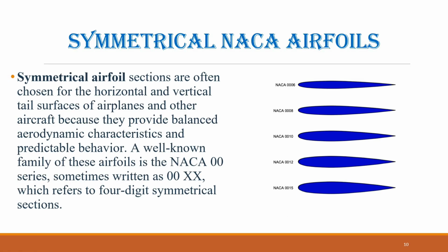Including the nose radius is critical because it prevents the leading edge from being pointed, which would negatively affect the airflow and overall aerodynamic performance. By following these design principles, the NACA 00 series airfoils provide a reliable, symmetrical shape suitable for tail surfaces and other applications where a camber-free profile is desired. These airfoils are widely used because they combine simplicity, aerodynamic efficiency, and ease of construction.